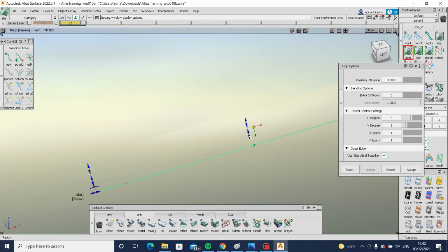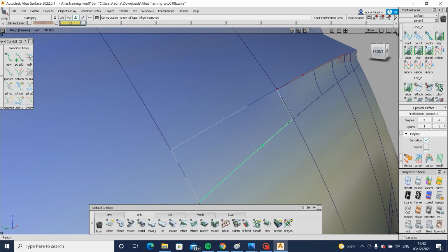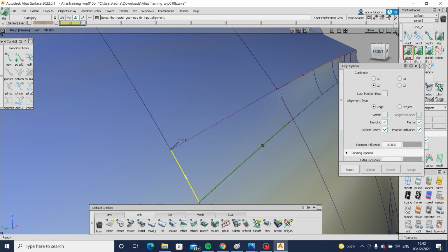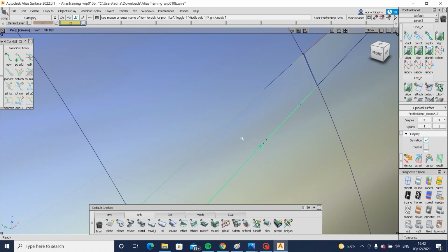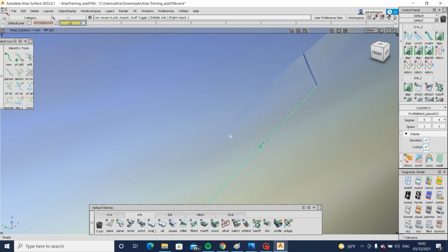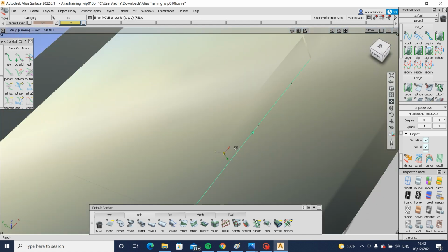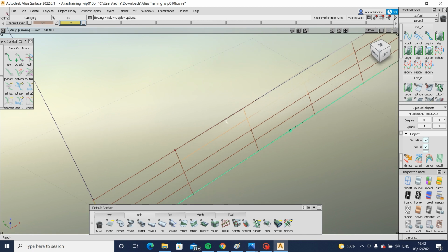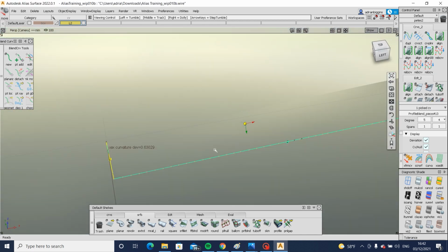And it's gone very negative there, which is annoying, doesn't need to be. We'll make this curvature on this edge as well, that'll help. A little bit, not really. Let's tweak it individually. Locally, I'm just pushing those CVs in a little bit and it's gone much smoother. Still not what I want. Maybe I've gone too far with this one. Better.